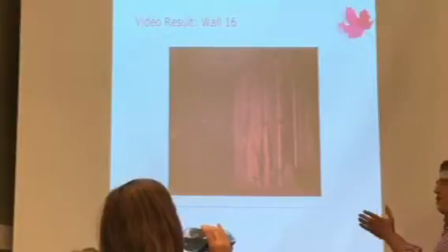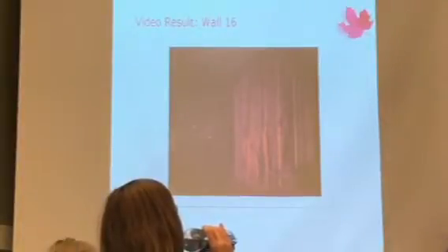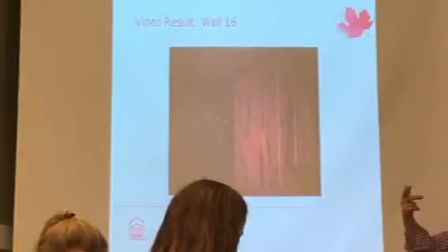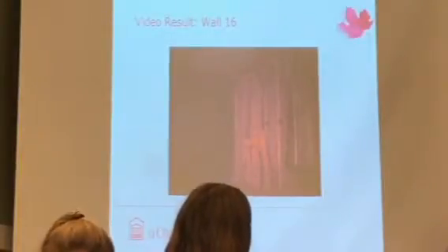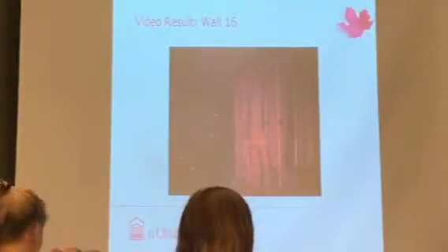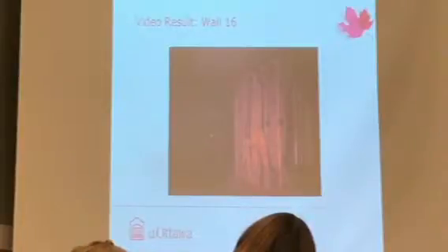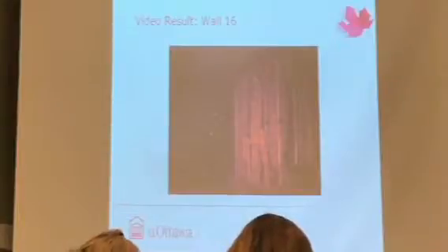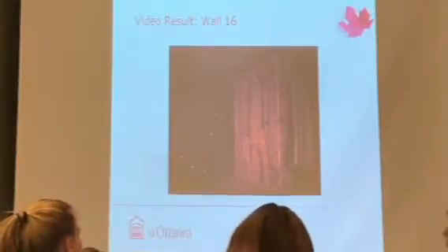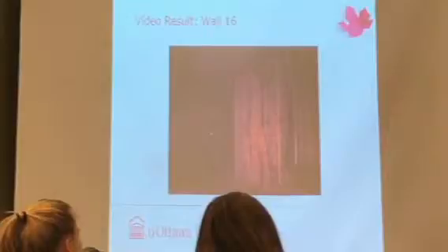So this is another one that was really interesting. We said, instead of transferring the load from the sheathing to the stud and breaking the stud, which would ultimately give us the highest capacity we can have in the wall. What's the highest capacity? It's by breaking all of the studs. We said, what if we do something else? Still prevent debris from happening. What if we sacrifice the sheathing? Let the sheathing break, let the studs still stand, but we'll catch whatever debris comes out of the sheathing.